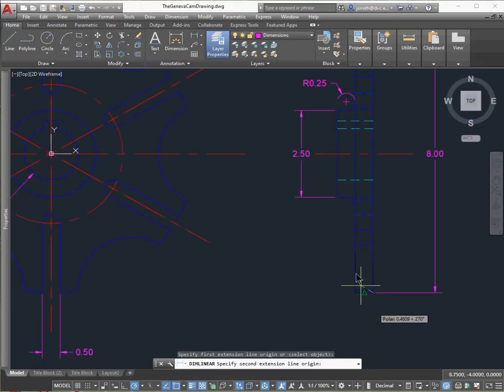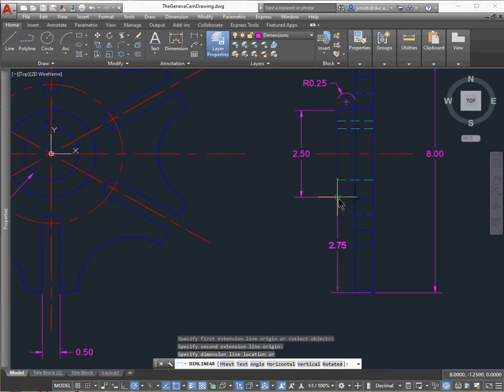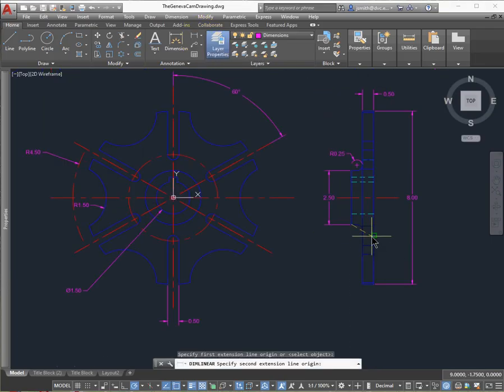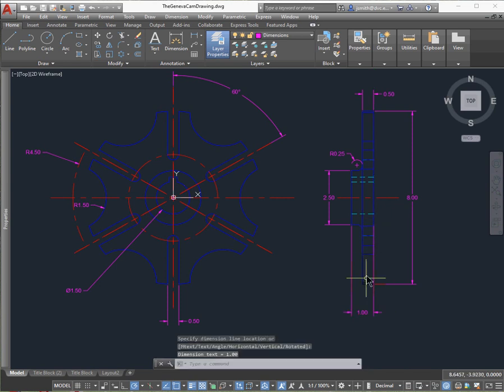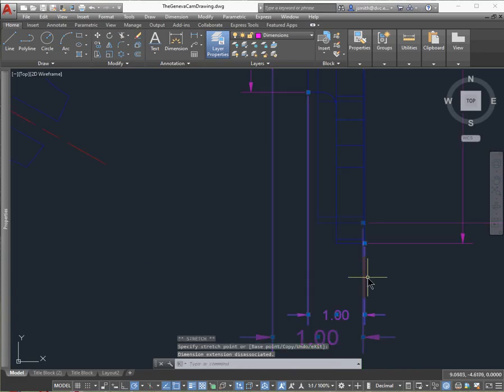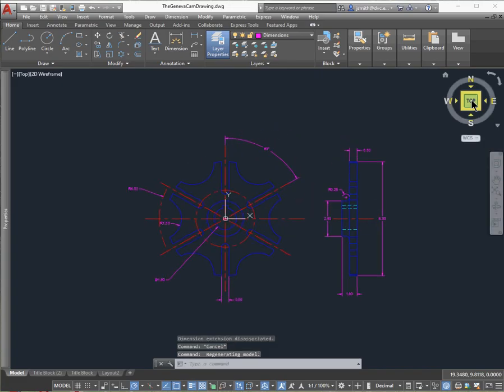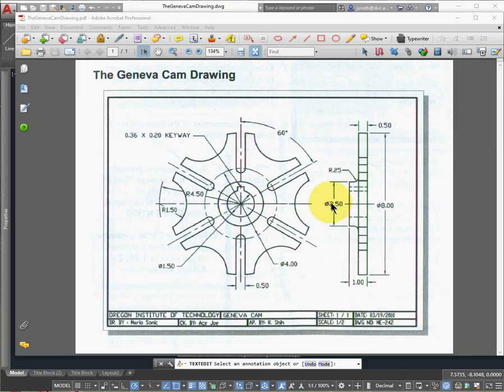All right, so you want to just check with the final drawing, make sure that you have all the dimensions that you need here and everything's accurate. All right, let's do that one again. And so I'll drag that. We don't want it in the middle of the part. We want to have it snapping on the end, so that's fine. And the tolerances I've already set, so everything looks good here. All right, just verify everything.